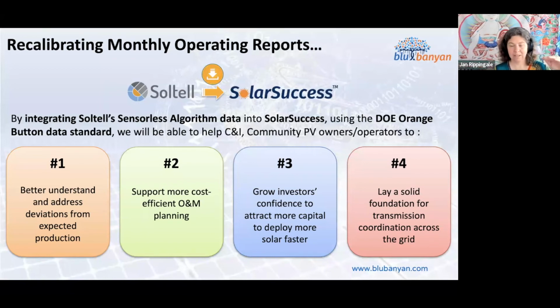And so the net metering and the 10 to 20%, the tier 3 readings, really doesn't scale as we need to coordinate as we get a larger install base across the world. So we need that to understand how to make cost-efficient decisions. If you have 90% and you only have a 5% deviation and it's 85 to 95%, there's probably some soiling, and you can decide, probably based on some trends, whether or not you think it's time to go out and wash your modules or whatever it is that you need to do next.